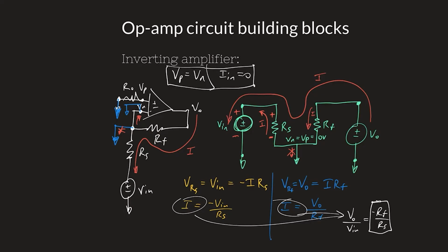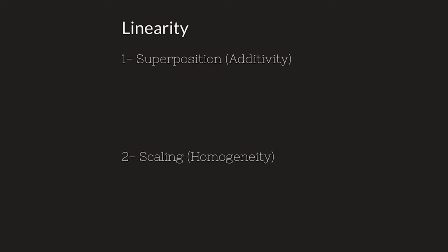What use do these have in general? So let's say you have an input that looks like this. Then for the inverting amplifier, let's say you have a gain of 3. The inverting amplifier is going to amplify this by 3 and invert it. And then the non-inverting is obviously the exact same idea, but it's just not inverted. But what if we wanted to do something like take the difference between two different signals, find a difference amplifier or a summing amplifier or whatever?